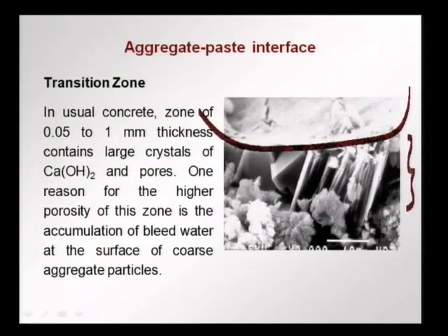So, it affects both the strength and durability. Also, we find that this is where bleed water could have accumulated, leading to this porous zone.